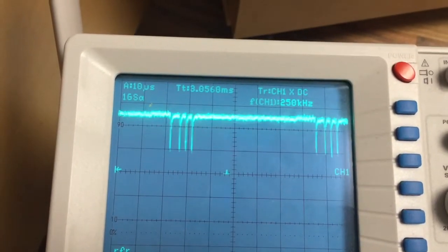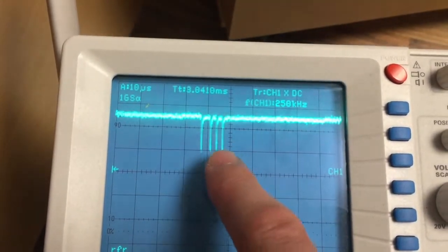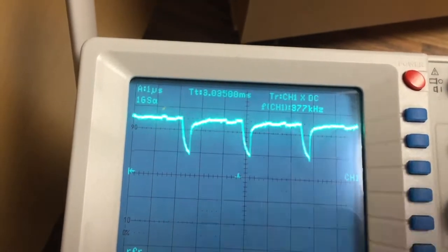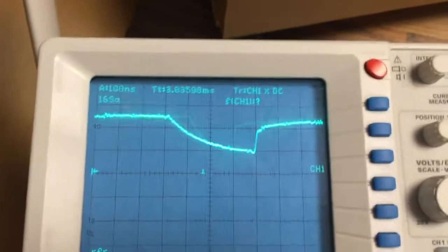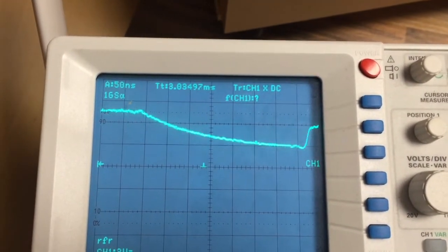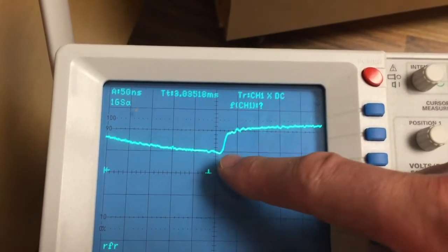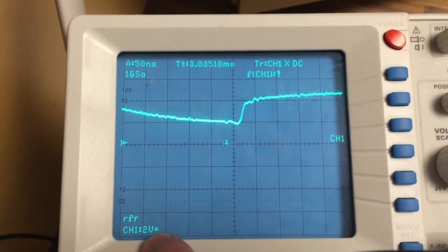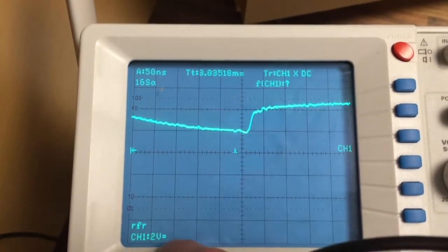It's high most of the time, as we saw with the logic probe, but there are some moments where the signal actually looks like it wants to turn to low. But as you can see here, when it is maybe wanting to turn low, it is still at a level of 2 volts, because one line is a difference of 2 volts.